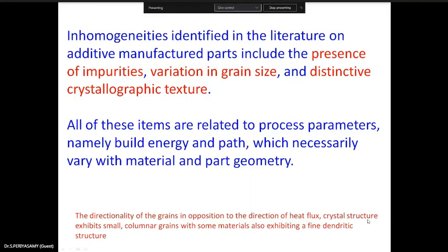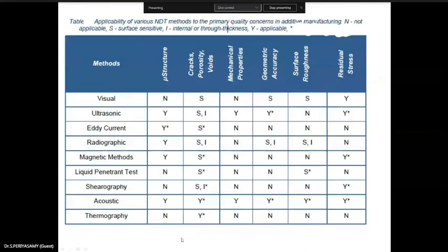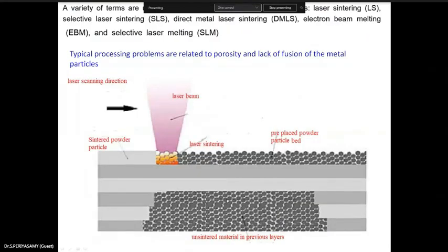If the process parameters go beyond that, that is the specific energy, you have a standard formula. In that standard formula, for each machine, you have to follow the range. That table I have also presented here. So if anything is varied, you can have defects. That is something you have to consider. Then the probability of detection data: you have very little data. Even if you are going for machine learning or something, the data available for AM is very less, so here you have to increase it.